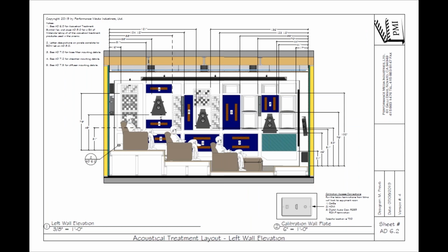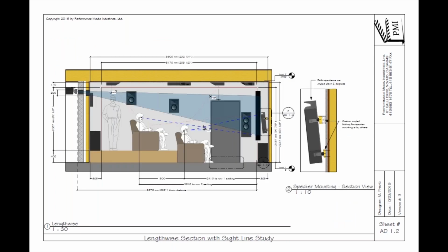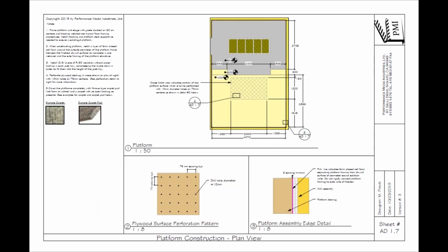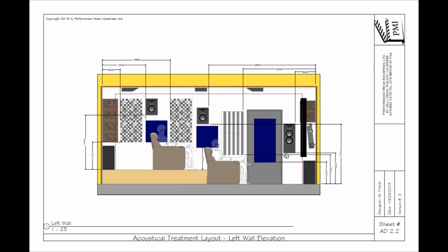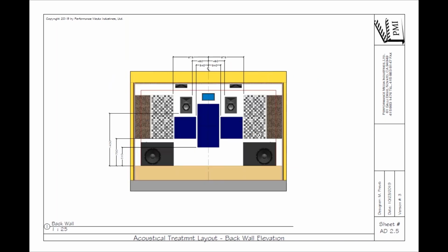So I'm just zooming forward through tons and tons of rooms. Okay, so this is a room where we did this one thing. First I'll go to the treatment lateral view of the room. So here's another room, 2 rows of seating, a wide channel speaker, absorption, 2D diffuser, absorption, 3D diffuser, all of that. Starting to look familiar. The front wall is using our Deco absorbers as low frequency absorbers. The right side is 2D diffusers, absorbers, 3D diffusers. The back wall is absorption in the middle, 3D diffuser towards the outside.